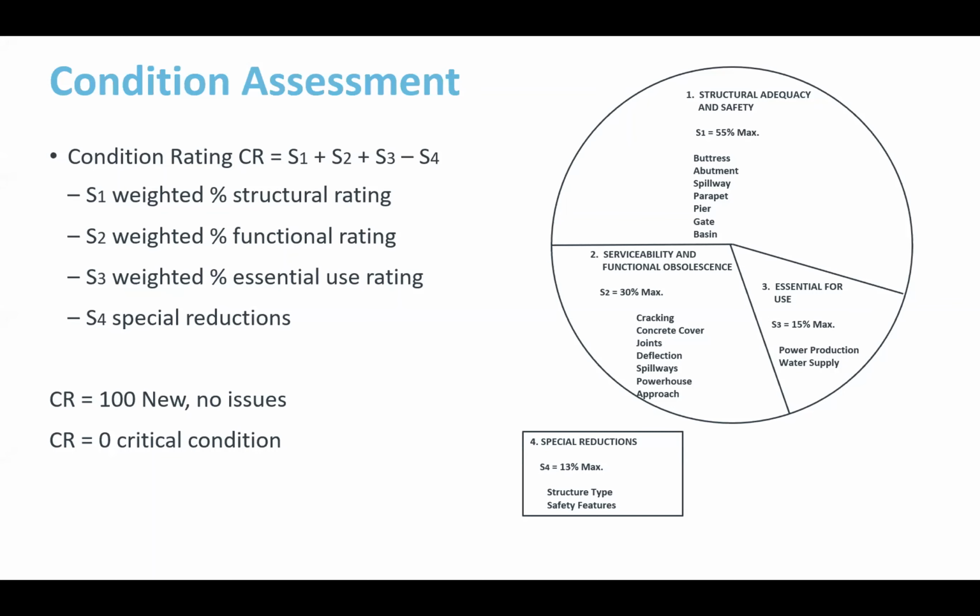I mentioned before, under the purview of the TCEQ, you have about 4,000 dams. Total dams in Texas about 7,000. So you can imagine we need a system in place here where we can at least rank and prioritize these in order to get a handle on which ones need to be addressed first. Otherwise, we're kind of at a loss. So if we're at a D right now, how do we get ourselves above a D? How do we get ourselves to a C, B, and up to A? We need some type of prioritization ranking system and be able to make some management decisions in the condition assessment process.